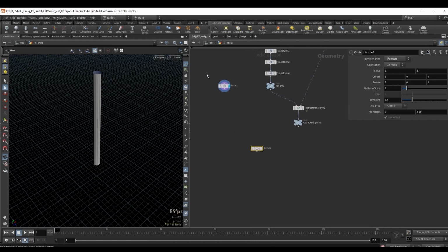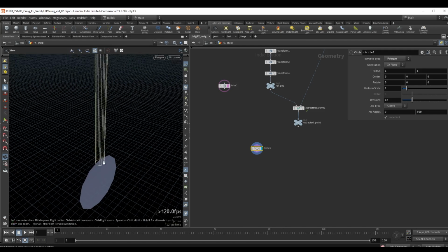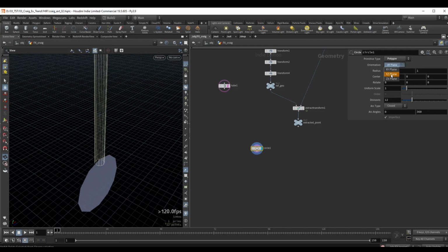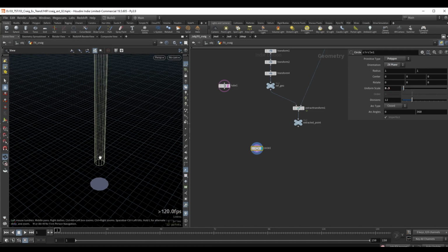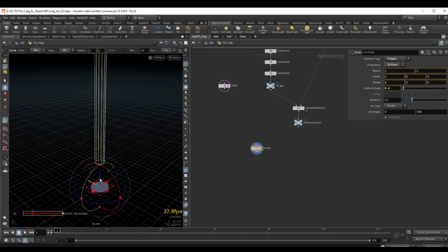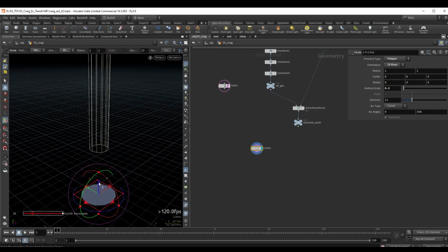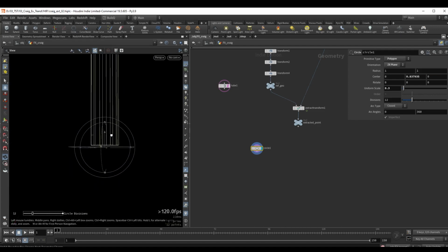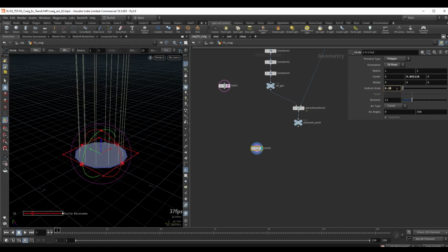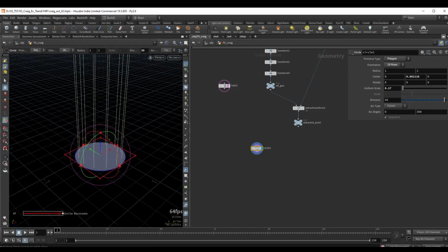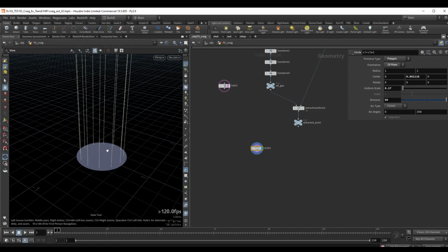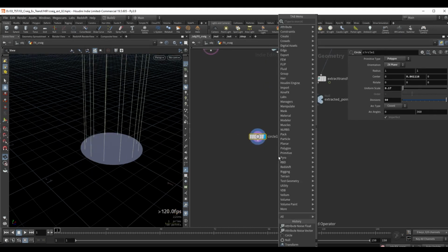And for our flaming spear effects, let's go ahead and start with a simple circle. And let's go ahead and template the tube and look at our circle so we know how wide the circle should be. And let's go ahead and set the orientation to ZX plane, and we will decrease the uniform scale to maybe a value of 0.3. And also let's just bring this up to the base of our tube where we want our simulation to start essentially. And I will adjust the uniform scale further to match our tube. So this should be fine, and I'll just increase the divisions here, so this will be a good base for our simulation. From here we can do a scatter.